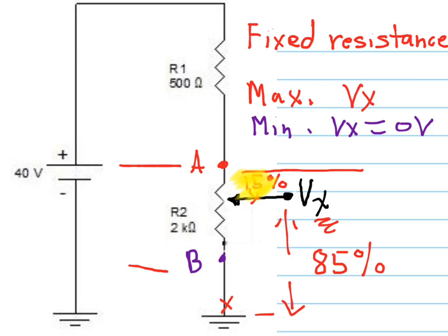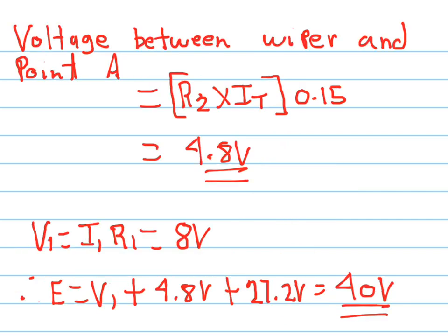Okay, so all I've really done, in one different color, green, is I've just taken what's the voltage across here, added to the voltage here, added to the voltage here, which is Vx, to make sure we get back to 40 volts. Okay, so we got everything.